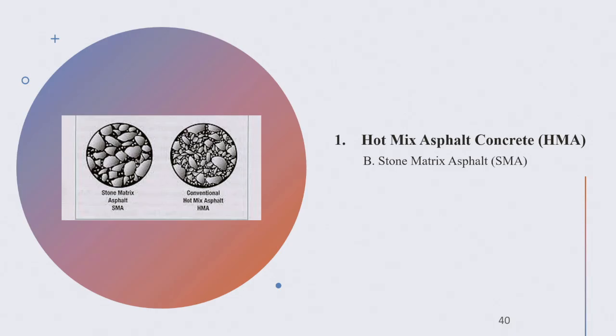They use this a lot, let's say in lots where you have a workshop or a lot of cargo stored, and some highways where you expect a lot of vehicles, like in trade or commercial corridors. Stone matrix is being used there. Now, you have to draw the line at which you stop overdoing it. Because if you overdo that, rutting is going to be happy with you. But trust me, your asphalt will crack in no time.